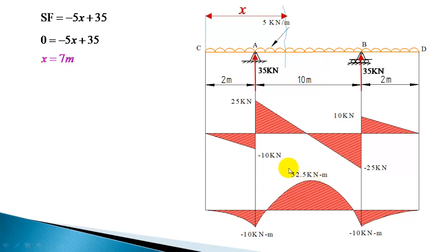And the bending moment is coming to maximum in the same section AB. So I have already taken a section. Now you can write down the bending moment equation. So we have already done the shear force summation, and shear force summation is a force summation. So these are the forces. Now you have to find out the moment for those forces. You only have to multiply these values with the distances where they act. So the load is 5x. Okay, that will produce a negative shear force. It's already there, minus 5x.